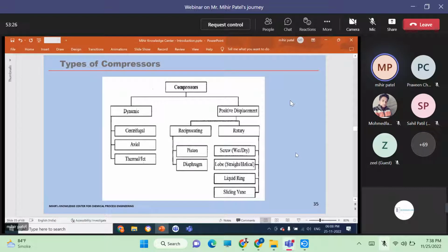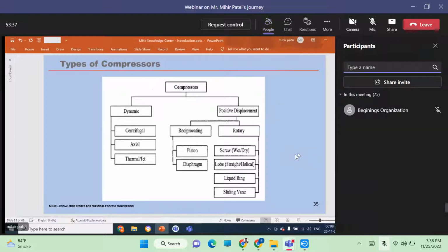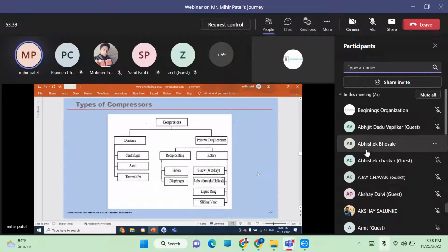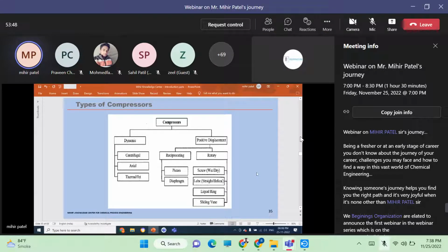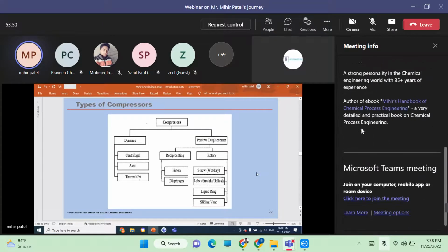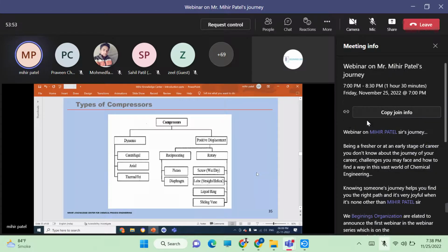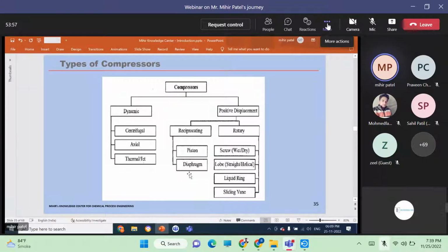So for example, in a fueling station, a vehicle fueling station, where hydrogen is used as a gas, normally the pressures are very high. You have 350 bars because it's a very light gas. So you have to pressurize more so that you can have more storage in kgs in that particular small cylinder in the vehicle. So in Europe and elsewhere, they are using 700 bars also. In India, so far 700 I have not come across, but 350 has started basically. That's where these diaphragm compressors come into play.